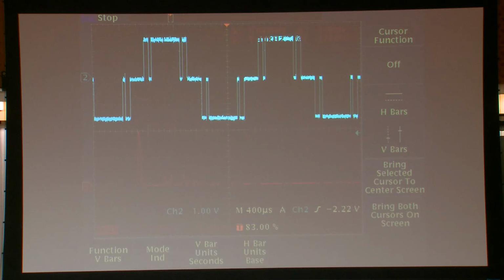You will notice the higher harmonics are getting higher in magnitude, but that's okay, because we care about the lower harmonics more, because it's easier to get rid of the higher harmonics. We'll need smaller filter components or smaller devices for applications. That's all.